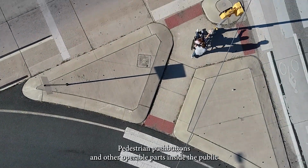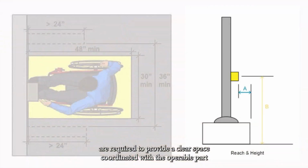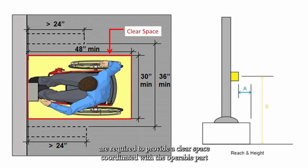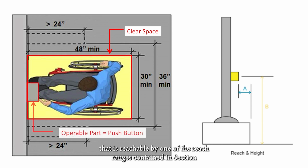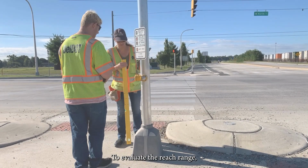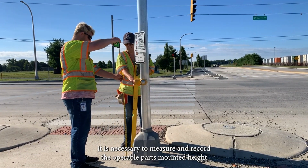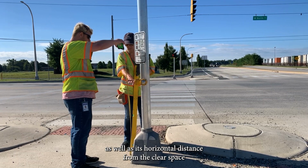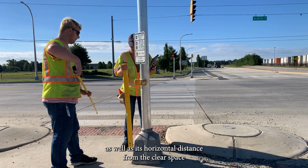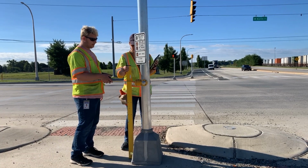Pedestrian push buttons and other operable parts inside the public right-of-way are required to provide a clear space coordinated with the operable part that is reachable by one of the reach ranges contained in Section 3.7 of the DelDOT PASS Manual. To evaluate the reach range, it is necessary to measure and record the operable part's mounted height as well as its horizontal distance from the clear space that is provided for the user to access the operable part.